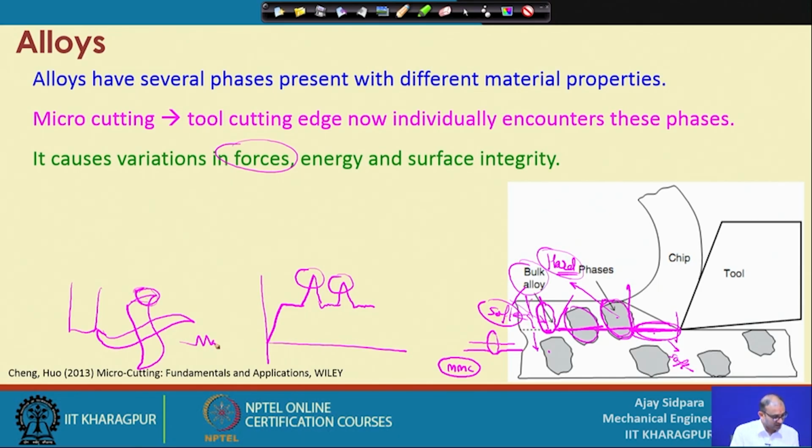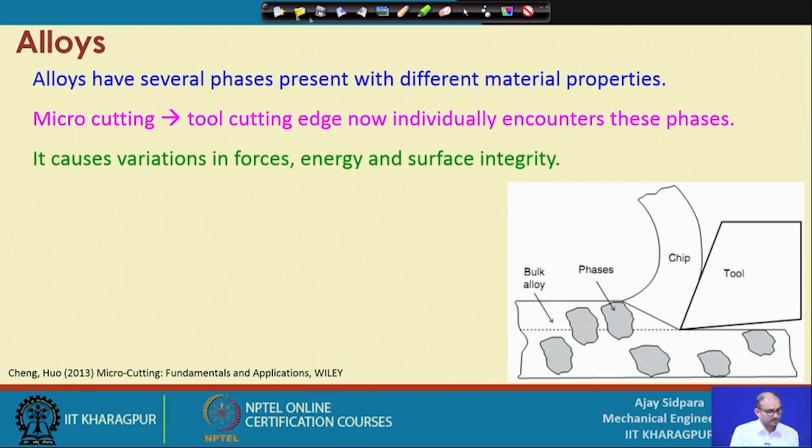So, you will not get that signal, and then you are getting 3 peaks continuously, because in this particular 360 degrees you have one angle where the material is not present. That means this particular angle will not remove any material because the edge is not present there. So, in this case you also get the signal, but with a single point cutting tool, or when only a single edge is cutting the material, then you can confidently tell what is happening in this particular case.